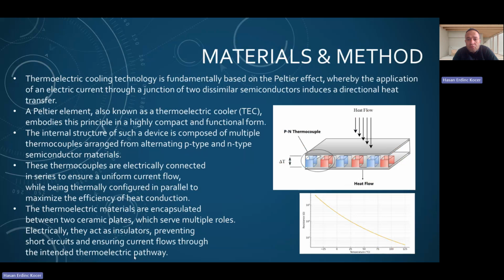We also use thermoelectric cooling technology based on the Peltier effect to control the temperature. The Peltier element, as you know, is a thermoelectric cooler. The principle is that when we apply electrical power, the PN thermocouple layers show a heat flow.